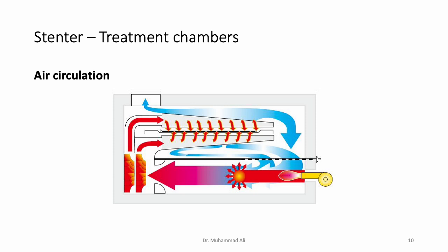There are reasons for that, because let's take the example of simple heat setting of fabric in the Stenter. In that case, the moisture content will increase inside the treatment chamber when air comes in contact with the fabric. And if it keeps building up, then the evaporation efficiency will be reduced. And that is why a part of the air volume that is in the treatment chamber has to be sent to exhaust, and an equal proportion of fresh air has to be taken into the treatment chamber. And this is sort of an ongoing cycle.